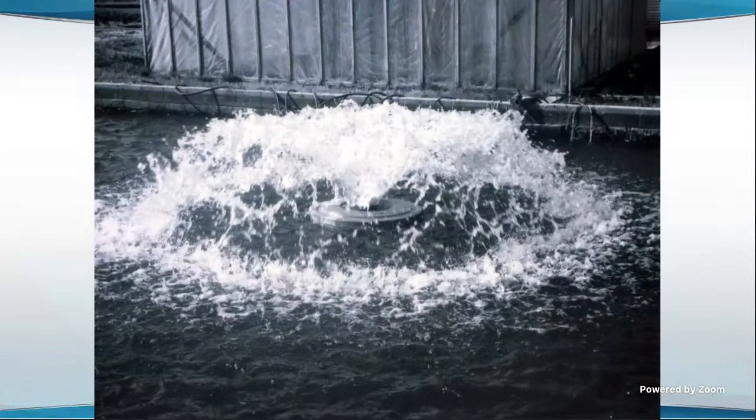The one that's throwing the water way up there transferred about 1/3 as much oxygen as the other. And of course, the reason is that it didn't pump near as much water. It just threw it up a lot higher. The water was just taking a joyride after it got about 3 feet high, and it wasn't taking on much more oxygen. So the problem is that most people that see aerators will pick the most inefficient one as being the most efficient because they're impressed by the fine spray or the water going way up in the air.